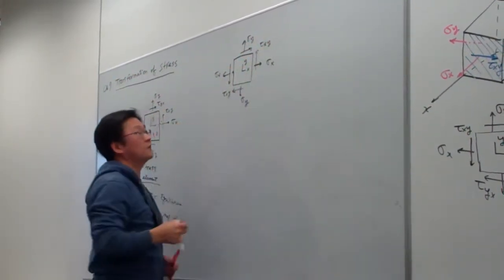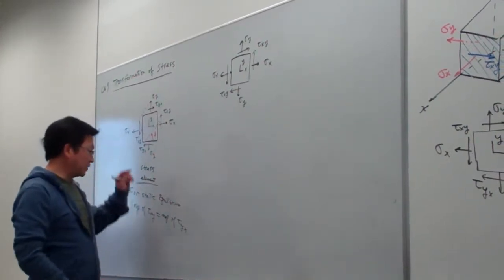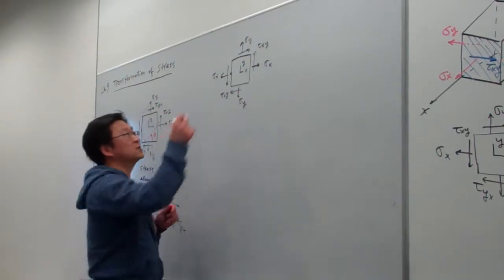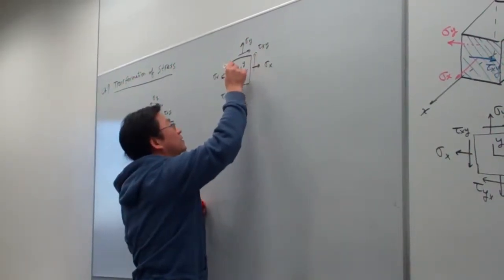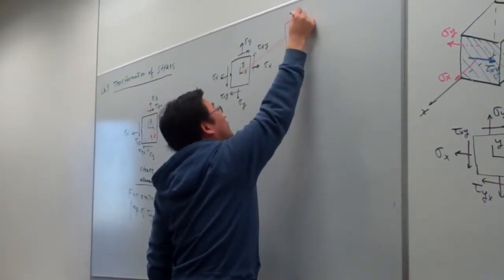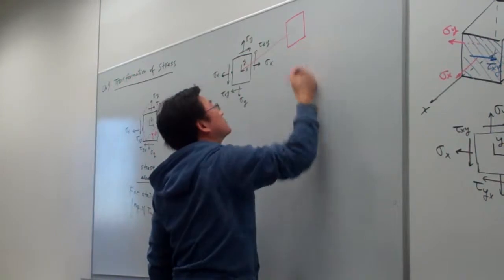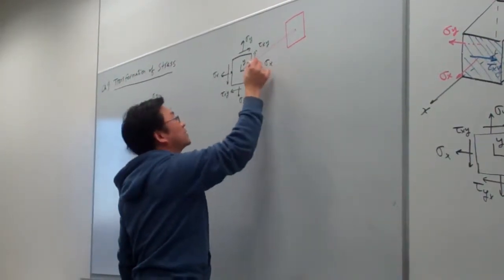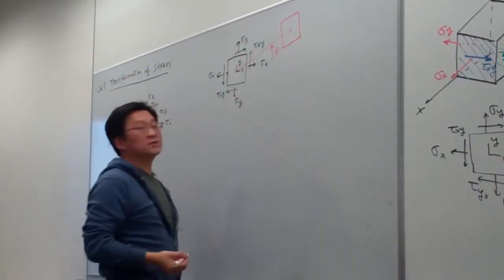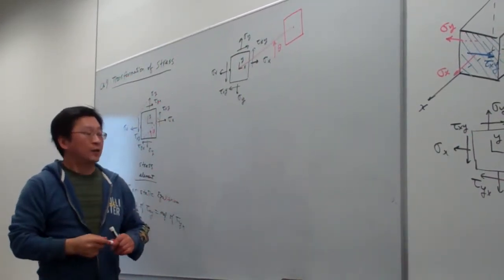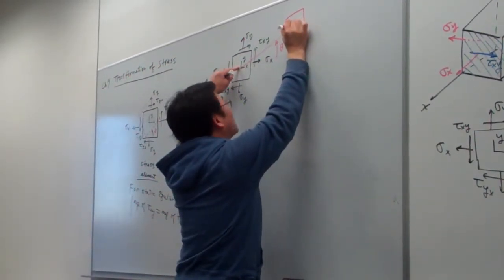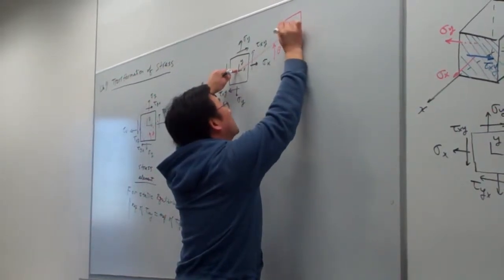So those are the given information, and then to represent the distribution of the stress in an oriented element is this. From here we extend the drawing so as not to overlap, and then from here, the new oriented element is like this. Okay, so this one has an angle, for example, here between the x-axis, we define the angle, say any angle theta. And then in this new orientation, with respect to our originally defined coordinate system, here we define say x prime and y prime.